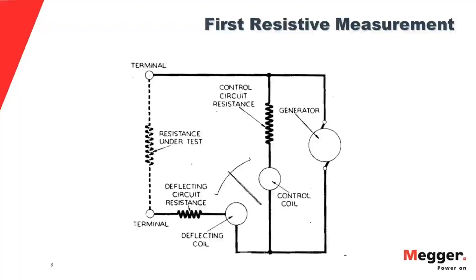They were set in a magnetic field at right angles, so they were working in opposition to each other, and the pointer then would strike a happy medium between these opposing fields, and then the measurement would have to be drawn against that. Initially, there was a spring at the base of the pointer that provided the necessary tension to keep it from free floating too much.